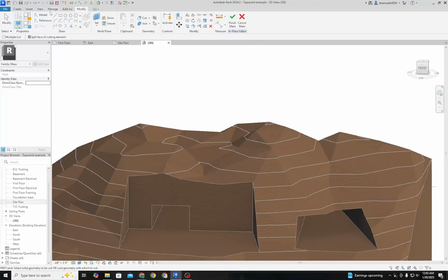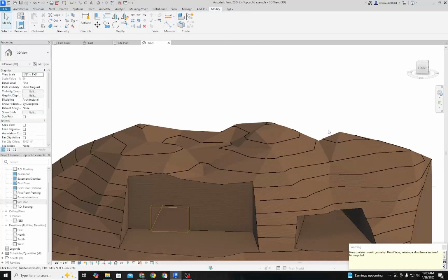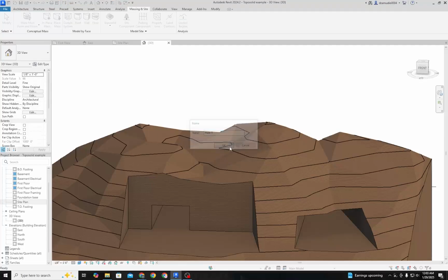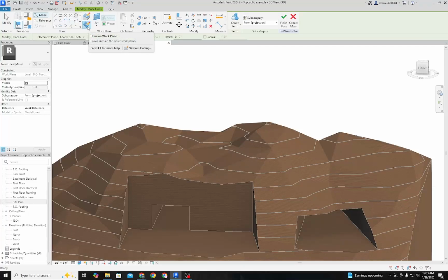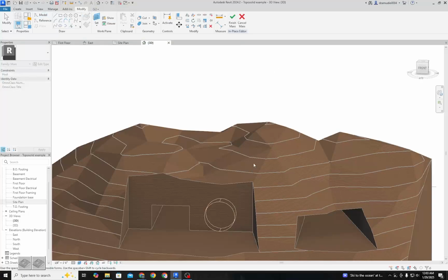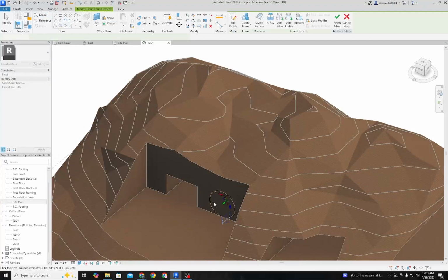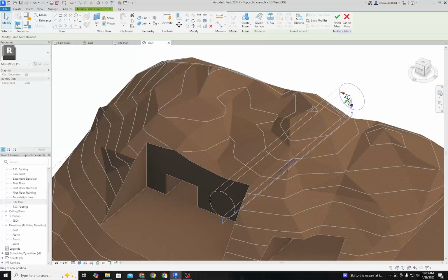Now if we wanted to create a circular object or some other form directly on one of these faces that we now have, instead of using place on plane, we'll simply do the whole thing, but do place on face, and it'll be the same exact procedure. You draw your shape, you extrude the void form, you use the arrow to move the faces of that void form to cover the area you want removed. And then once again, it's the same.